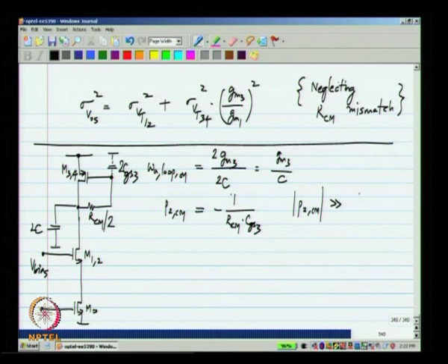And we would like this to be at a frequency much more than the unity loop gain frequency. Otherwise, what happens is when you have a common mode excitation, the output will ring. Now, there is a way to fix this, and that is to have a capacitor CCM across RCM.